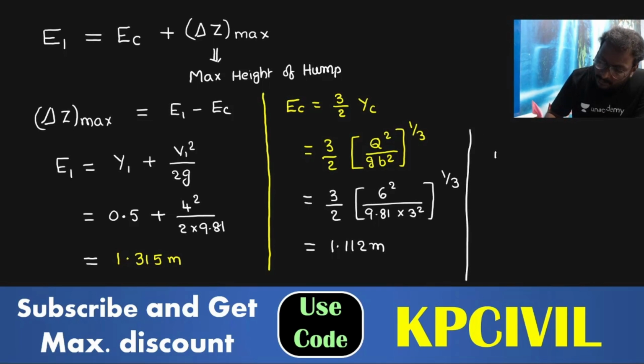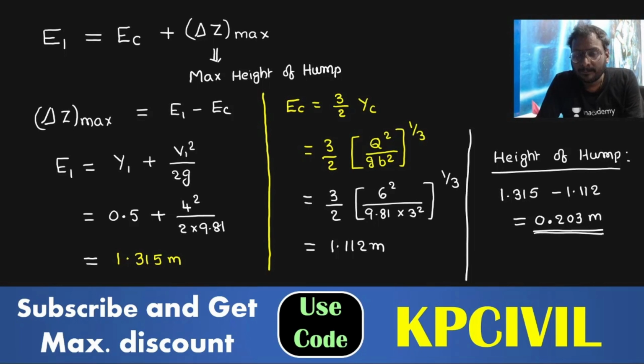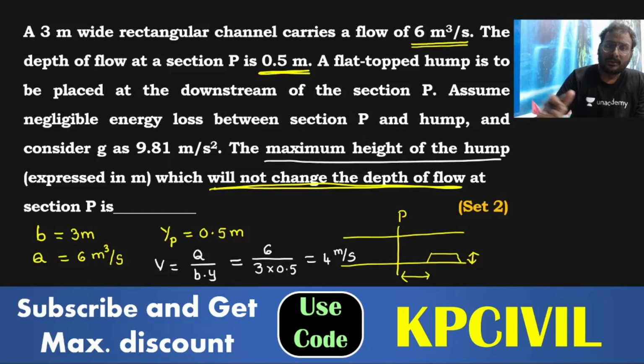EC is 1.112 meter. Now the height of hump, delta Z max. Height of hump delta Z max is 1.315 minus 1.112 meter, which is 0.203 meter. You understand it now? Height of the hump is 1.315 minus 1.112, equal to 0.203 meter. That is the answer. You write here.